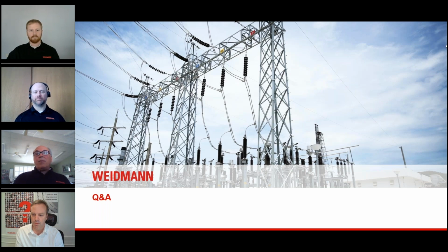That is even much better, well over 90% with Nomex spacer material. So for short circuit strength in a transformer winding, Nomex spacer is better, and the Nomex conductor wrap as well, because it's such a high thermal class of the Nomex. You won't get any aging of that wrap, which causes it to shrink over its lifetime. So using Nomex within the winding itself will allow you to have a much more stable winding over the life of the unit.